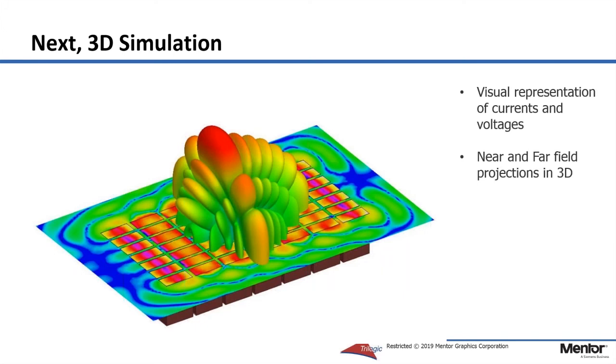So you really have some basic setup and configuration in your simulator, like with HFSS. It uses finite element modeling using adaptive mesh and a compliant solver to render really useful information. It could save you time and money by reducing the number of design iterations prior to production. And I can tell you from having done this for 25 years, I have very good job security from fixing and addressing oversights from customers that don't use these tools and don't use all of the utilities that PADS offers to avoid some of these noise issues.